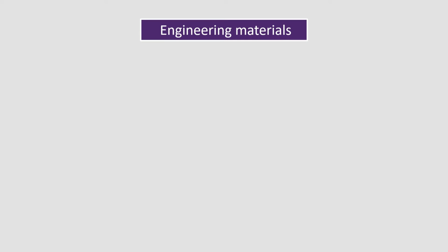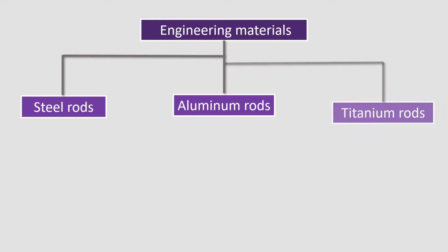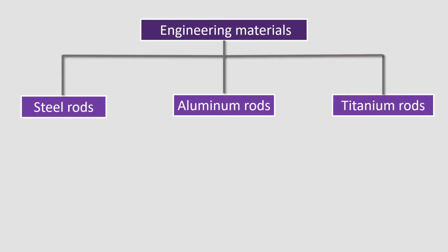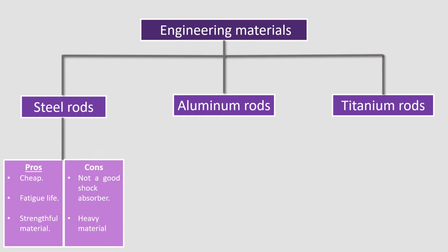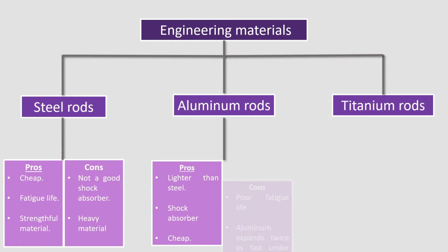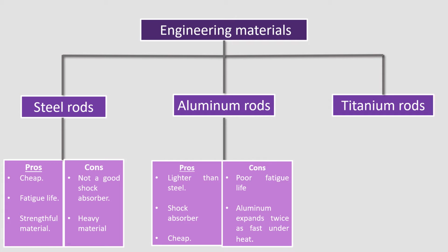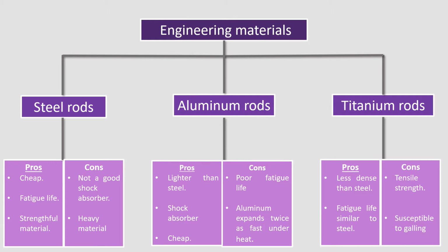It is also important to add the different possible materials for this piece, being possible the use of steel, aluminum, and titanium, being the best option steel, because aluminum rods need many revisions, and on the other hand, the price of titanium is very high and not optimal for this type of production. Steel rods can be cast or forged. Cast ones are okay for stock applications, but are usually a bad idea if you are interested in significantly increasing the power and torque output of your engine.